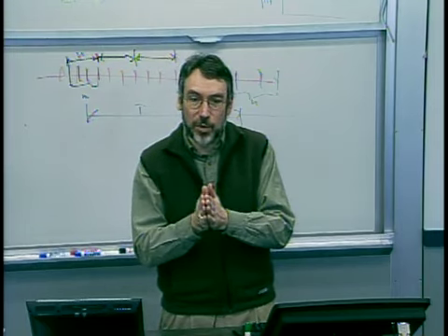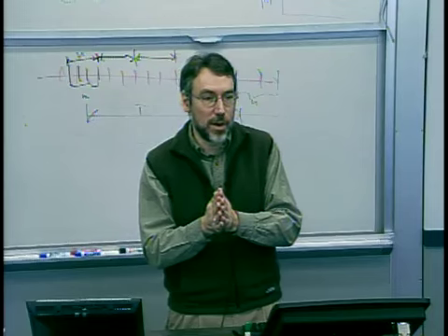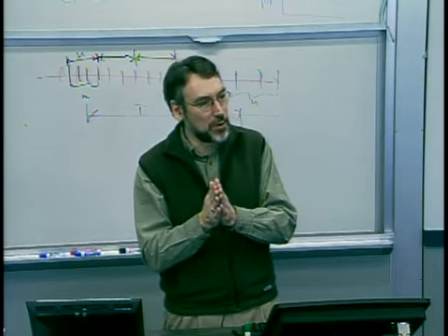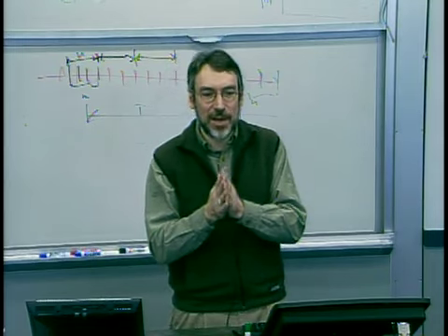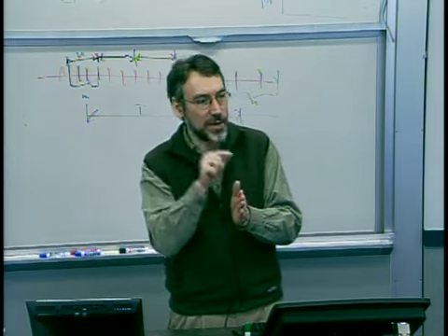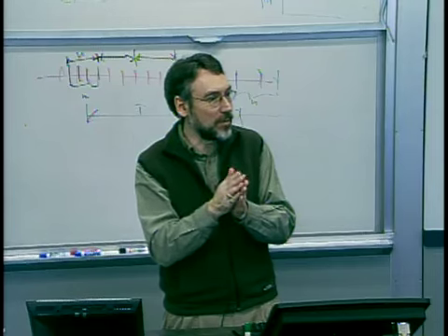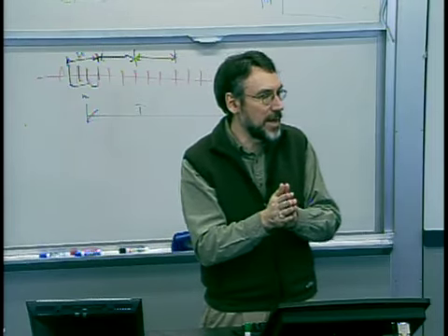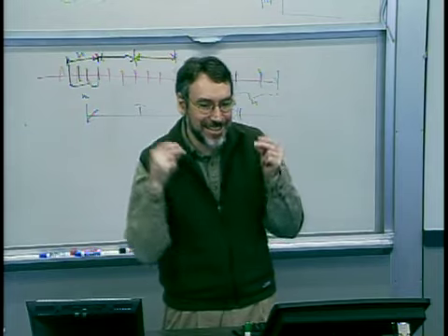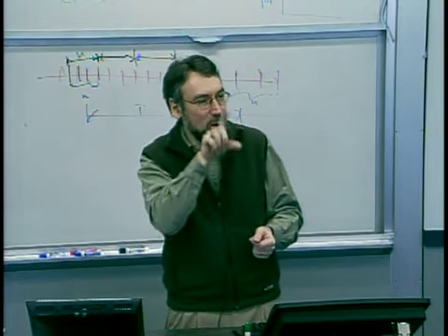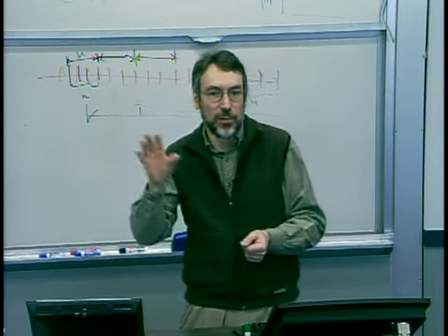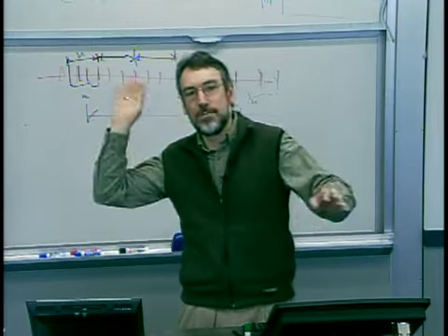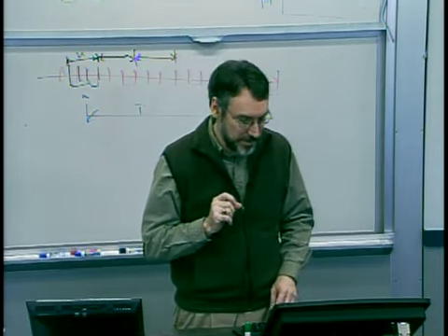And then finally, we'll also give you a little bit of a feel for a cumulative sum chart, where we aggregate deviations from the mean because we're really looking for, was there a small change or is there a small drift going on in the process? And how do we increase the sensitivity to detect that small shift as rapidly as possible? So we'll talk about charts that are really meant to squeeze that average run length for detection down.